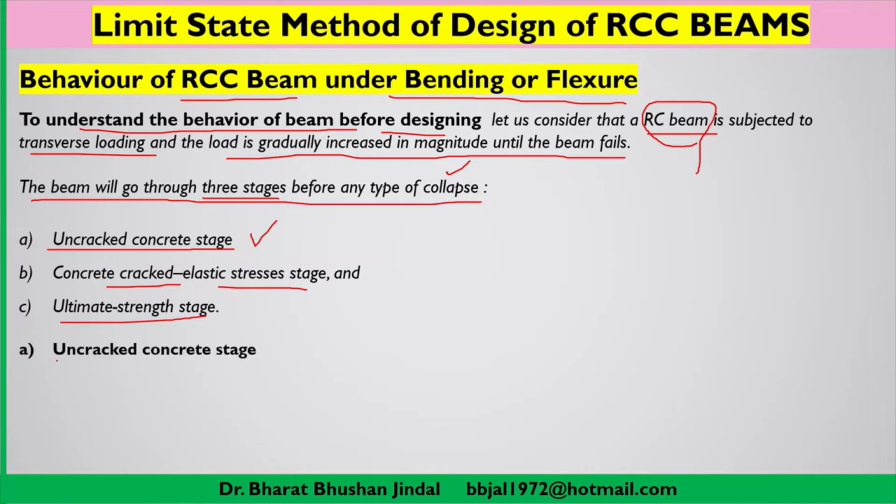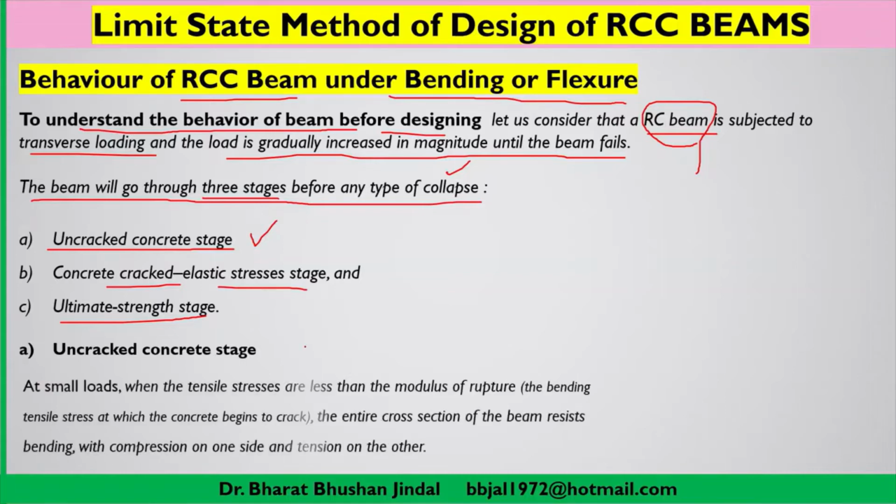Now let us go one by one. Very first is the uncracked concrete stage. Definition or elaboration: at small loads, as we have already said, we are increasing the load gradually. So when the load magnitude is small, the tensile stresses which are developing in the member are less than the modulus of rupture.